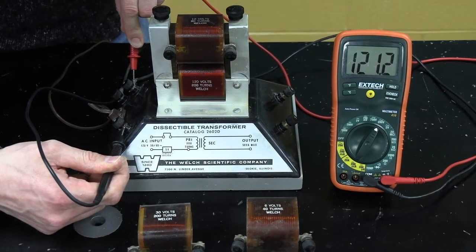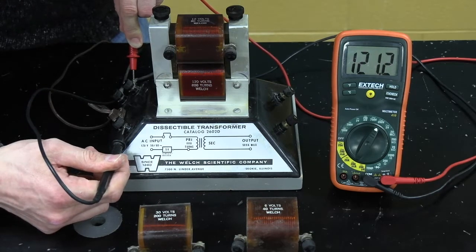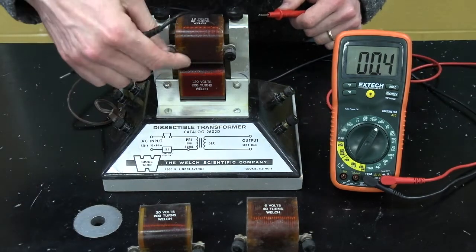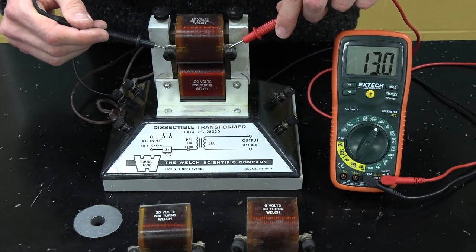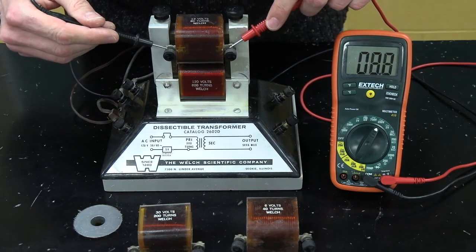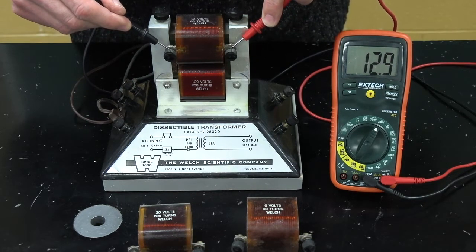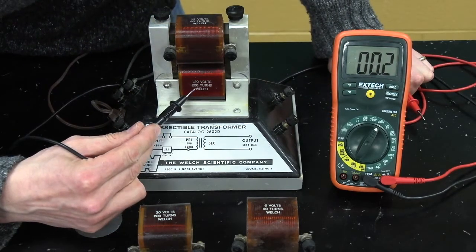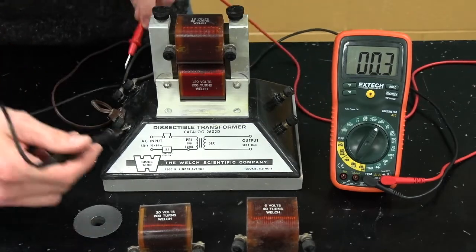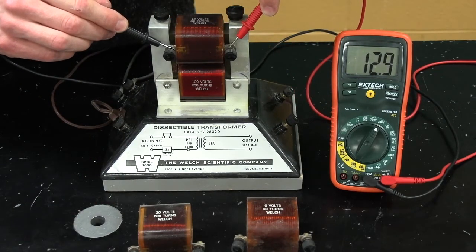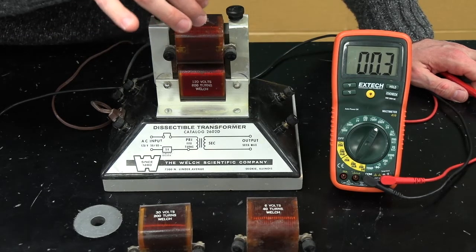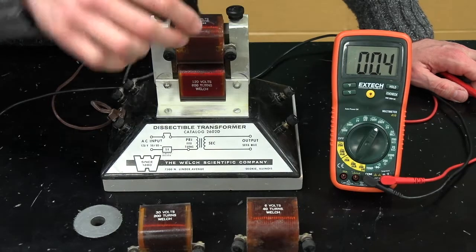I mentioned this already, that the wall outlets in America operate at 120 volts, so that's all I'm measuring, the voltage out of the wall, which is what's going into this primary coil. Up here, though, the secondary coil, if I go like this, I see I only get 12 volts, 12.9 instead of 120. Let's just say 12 and 120, just to make it easy. You might notice 800 wire turns, 80 wire turns. There's a 10-to-1 ratio in the number of coils. And we've got 120 volts and 12 volts, about a 10-to-1 ratio in the voltage. So that's essentially how a transformer works. By making fewer wire wraps up here, you get less voltage than the primary.